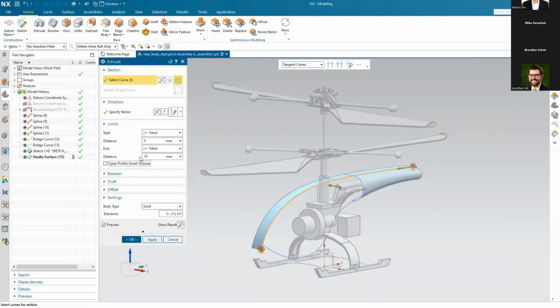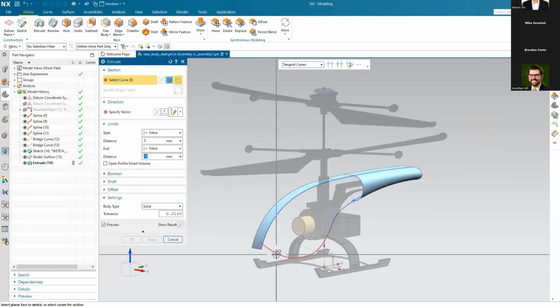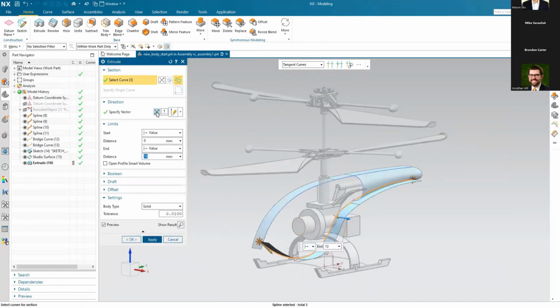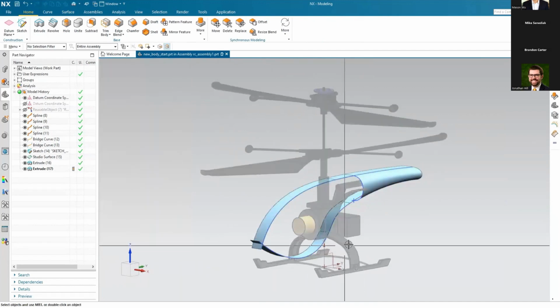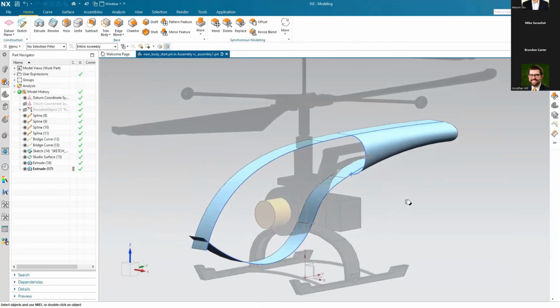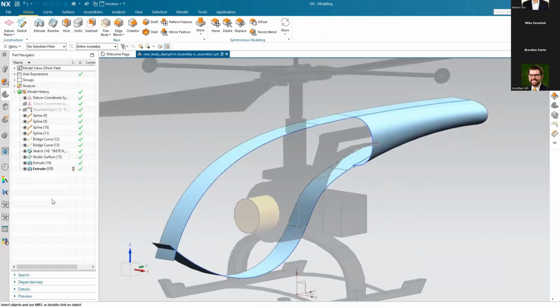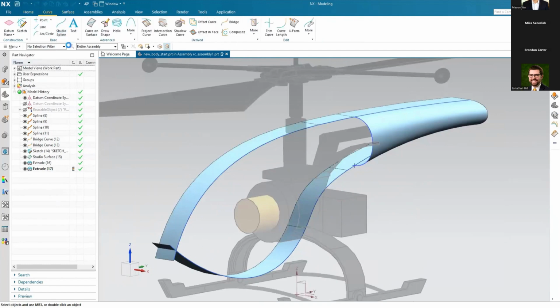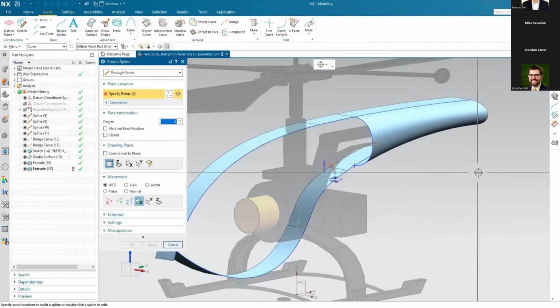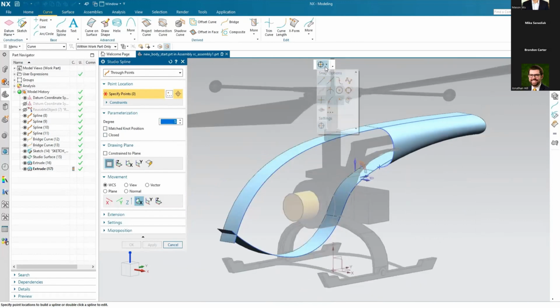Here are also some things that, when you're doing anything that is symmetric, you want to make sure over those interface planes that things are good and smooth across there. Sometimes you can create reference geometry. We'll use this to make the selection when we create this next segment of the surface. That way it will maintain that tangency and the curvature across there, so again, getting a good, high-quality surface.